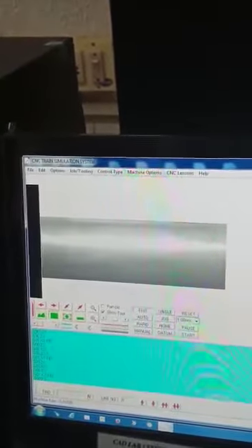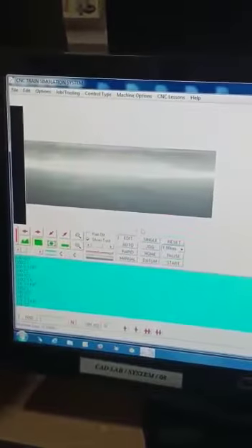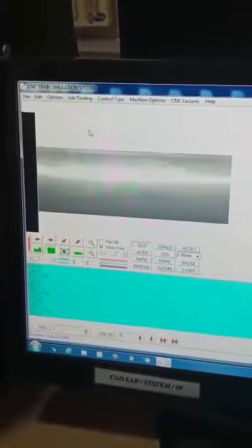Again it's coming to a reference point, G00 X23. So both your positions, X and Z. These are the 2 dimensions for your facing. One is your Z axis and the other is your X. X is the diameter, and Z is the length of the job. So now again G01 X minus 1 F45. So it must cut 1 mm. G00 Z3 and G00 X23.